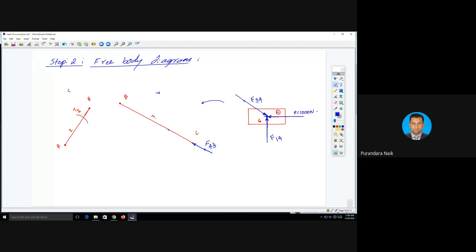It is very easy, correct? So if you know this force, you just write the same amount of force here by changing the numbers. That's all. Because I'm considering link number 3, the force due to link number 4 on link number 3. Any doubt?